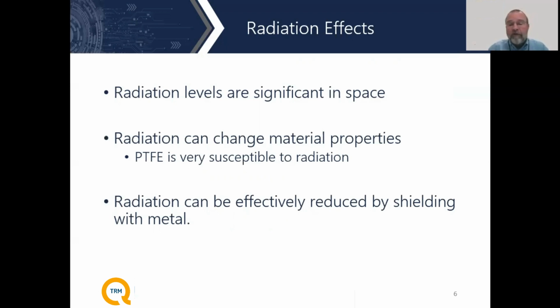So, for example, if a component is buried deep in the middle of the satellite, you need very little shielding in place to make sure that the Teflon holds up over time. But if it's out on the edge of the satellite, or right behind an antenna array, or mounted on some sort of an arm somewhere, then you need much more shielding in place to make sure that the Teflon doesn't break down over time.